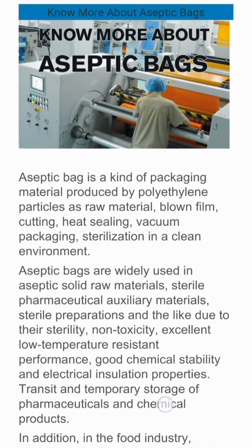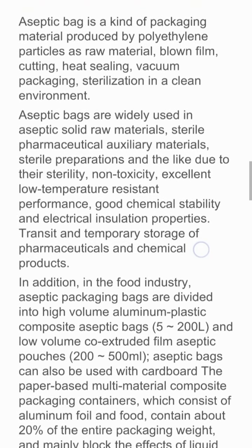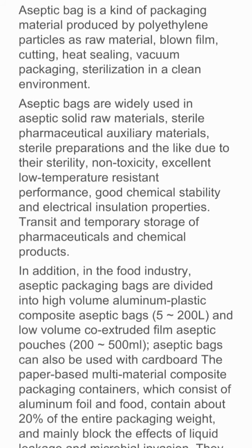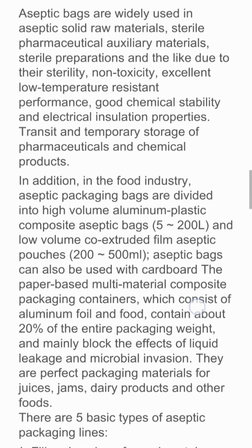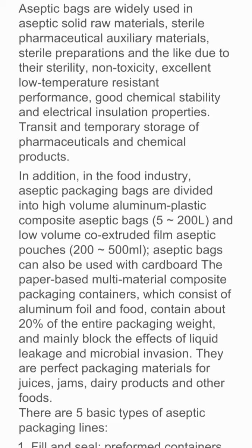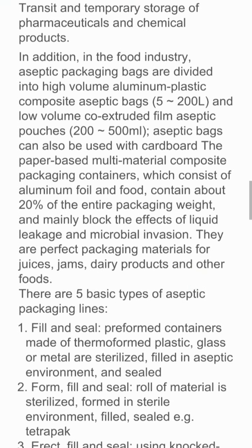Aseptic bag is a kind of packaging material produced from polyethylene particles as raw material, through blown film, cutting, heat sealing, vacuum packaging, and sterilization in a clean environment. Aseptic bags are widely used for aseptic solid raw materials, sterile pharmaceutical auxiliary materials, sterile preparations and the like due to their sterility, non-toxicity, excellent low-temperature resistant performance, good chemical stability and electrical insulation properties. They are used for transit and temporary storage of pharmaceuticals and chemical products.